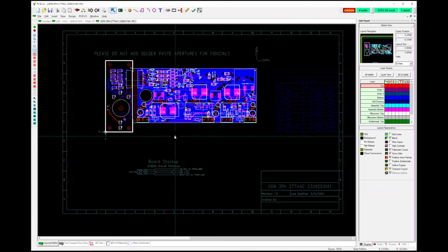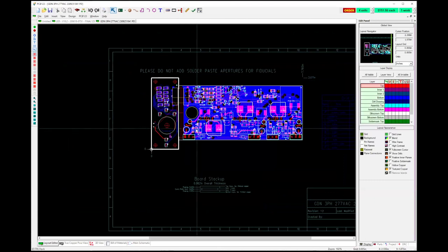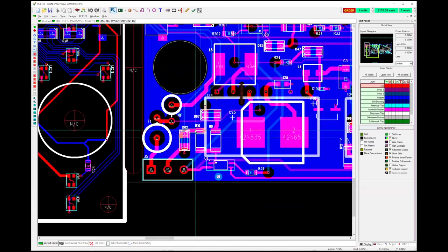And then I'll take a paper copy of the schematic. I'll just print it out to whatever size I can see the reference designators, and I'll select the parts by reference designator and move them to where I think they should go. So to select a part, you just type an F to find, and then you enter the part name. Let's go with something easy. R10. That puts your cursor right on the R10. You can zoom in on it, take a look at what's going on, and then place it where it goes.